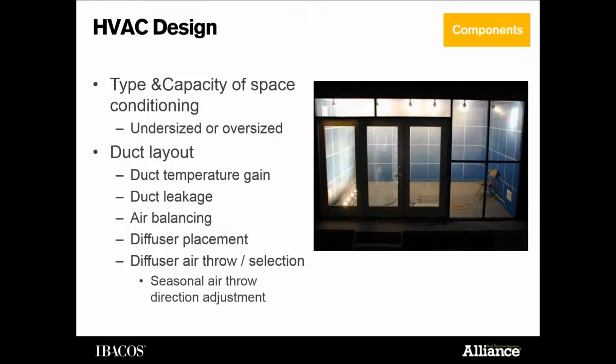But understanding what type of heating and cooling system the builder wants to implement in this home and the capacity is very critical in what we're trying to do here. Obviously, we've had this oversized versus perfectly sized for many years, and I think the industry is getting better at actually sizing these units according to the right Manual J. But these are things that the metric will have to consider through ACCA Manual J, Manual D calculations.